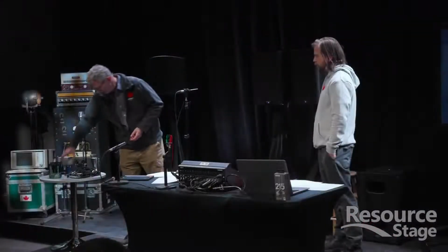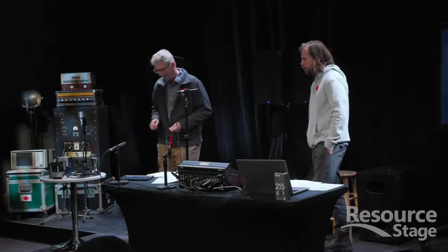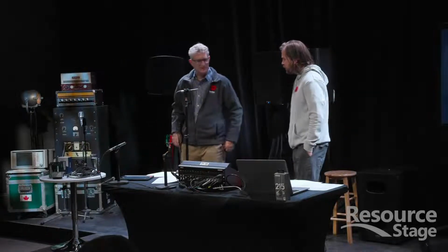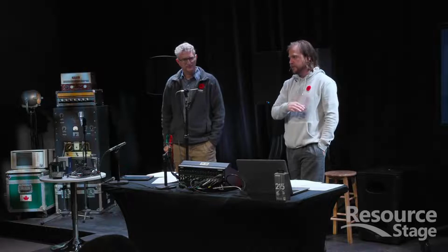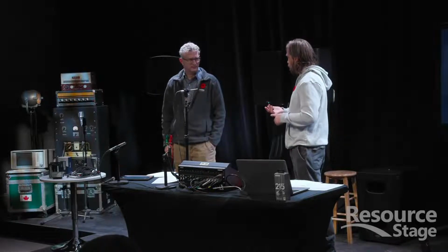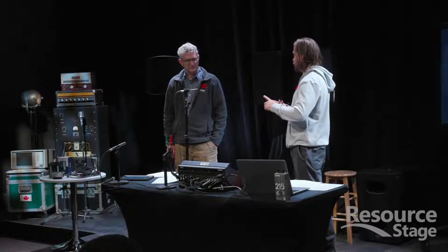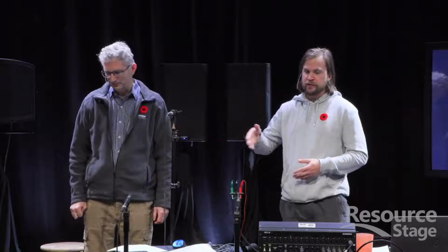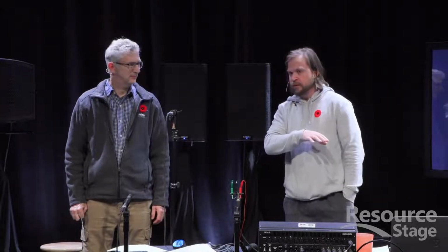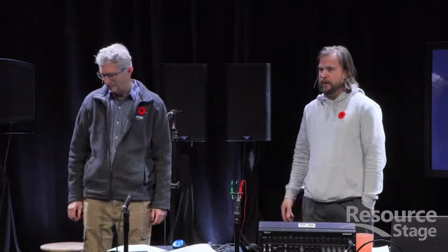Have I covered everything about direct boxes? I think so. The reason why we're always selling these and always putting them into systems is going back to gain structure and signal level types. You talked about laptops, you've talked about bass guitars, mandolins, keyboards, all these different things that you're going to be plugging into your system, all likely to have a wide variation of level. And what we're doing is isolating those signals, dropping them down to mic level to where the console wants them, and starting gain structure with the right foot. So DIs are very handy for that reason.